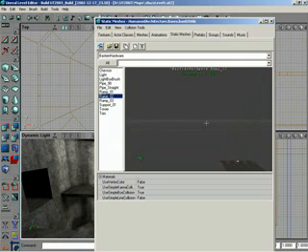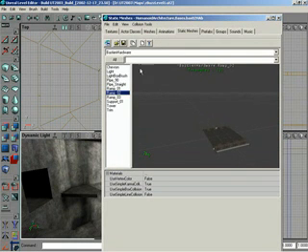So let's spend just a second and talk about this static mesh browser right here. As we said in the very beginning of this entire VTM, static meshes are nothing more than geometry that has been modeled in another 3D package, textured and lit, and then brought over into Unreal Ed, or at least has been packaged up into packages that we can then load in and go through using this browser right here, find the one that we're interested in, and then load it into our scene. Now, this button would allow you to throw it right into the scene somewhere, or if you have it selected in the static mesh browser, it will appear in your right-click menu, which is how I prefer to add them. So with this ramp 02 selected, I'll close out the static mesh browser for now.